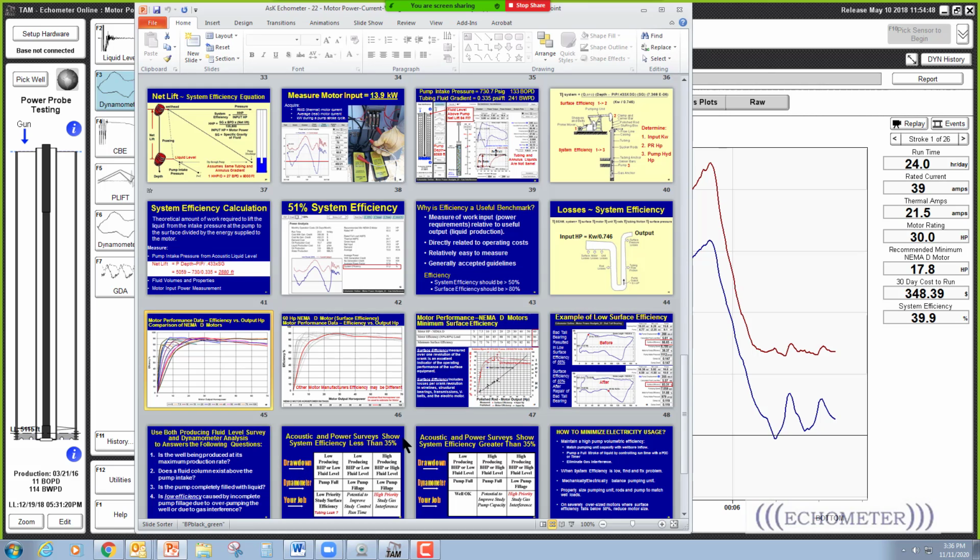In fact, in the presentation I did at ALRDC, I think last year maybe, in the sucker rod part, we talked about inefficient pumping, and we used the power probe to show that. So the power probe is an excellent tool when you're trying to analyze hydraulic pumping units, because if there's no counterbalance, then normally the efficiency is very low.